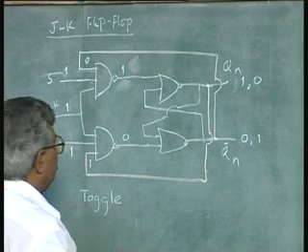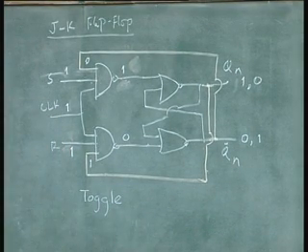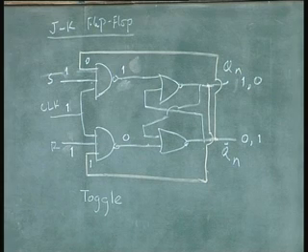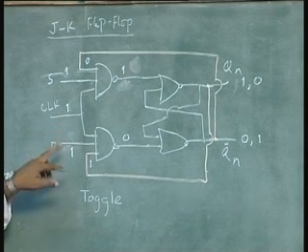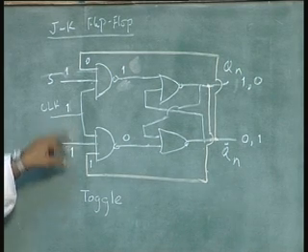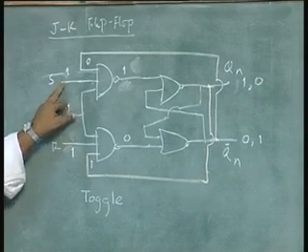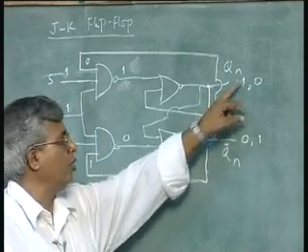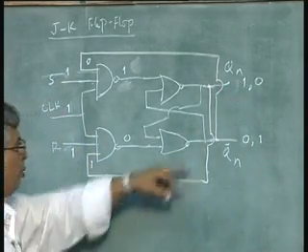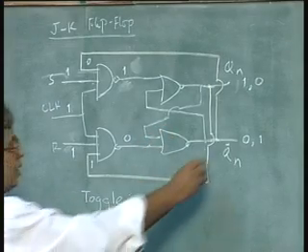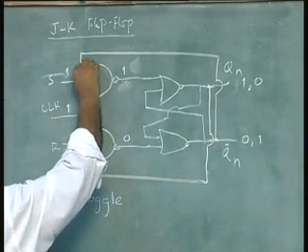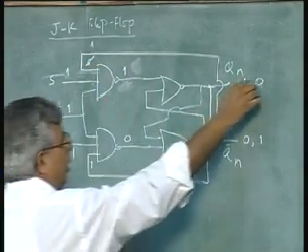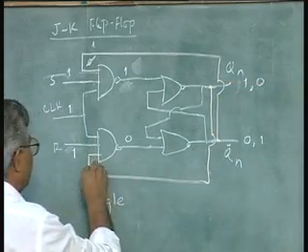But unfortunately this is not going to be all that simple, because the clock continues to be 1, input continues to be 1, but now we have changed output from 1 0 to 0 1. Remember, there is a feedback. This feedback gets this 1 back into this, and this feedback gets this 0 back into this.